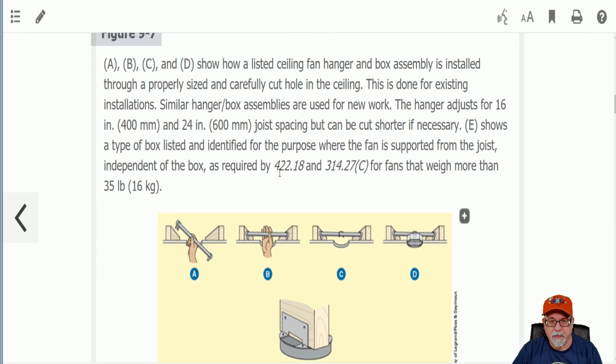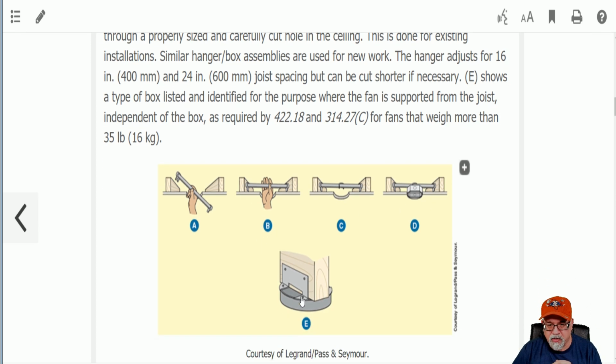And here's an example of a hanger designed to install it. And this is kind of the retro design. Sheetrock's already up. And you see here, you take the box down, you reach up, you put the bracket in there. The bracket has a holding clamp, and then you mount the box to it. This is also a hanging assembly. This is more like a remodel assembly. And of course, there are also other designs that go on the end of a stud.